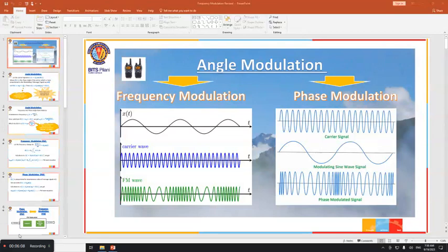See, these fundamentals are very important. If someone doesn't know what the phase angle of a waveform is, he will never understand entire frequency modulation. All of you know about the phase angle of a waveform, right? When you draw a waveform, what you see in a cycle is phase: 0, pi, 2 pi, 3 pi, 4 pi. What is that? Phase angle. The same phase can be written in the form of a frequency, that is the rate of change of phase. How much the phase changes per second is going to give you the frequency, right?